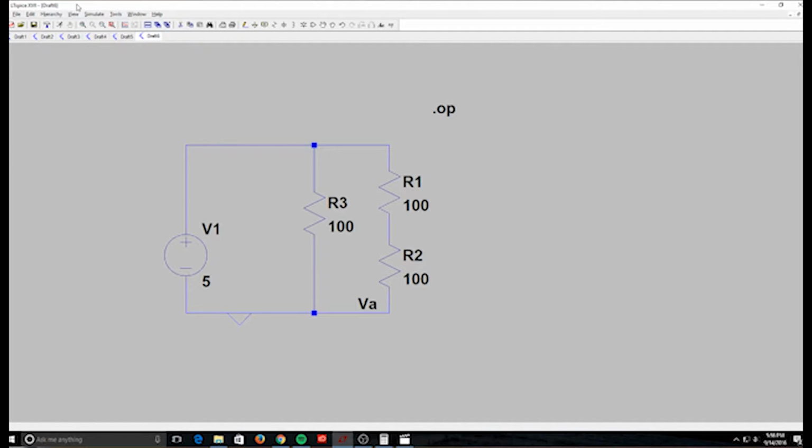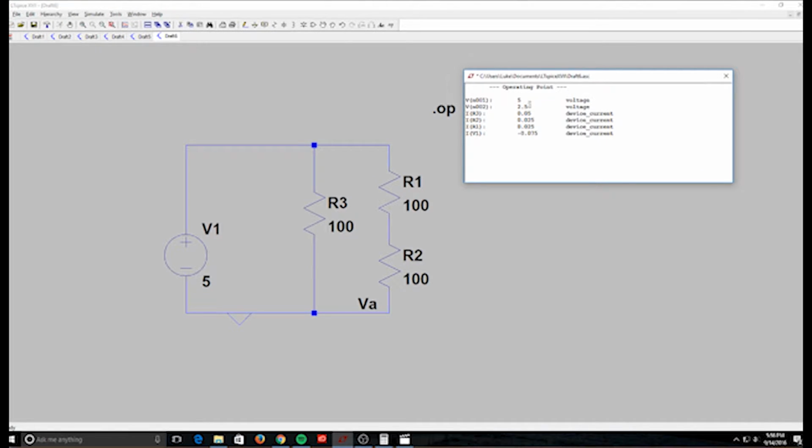Here's our last circuit with 2 resistors wired in series that is wired in parallel with a separate resistor by itself. We find that there's a 2.5 volt drop across all of the resistors. So if you end up repeating the math that Kaale ended up doing before, we get 0.25 amps of current going to the 2 that are wired in series, and 0.5 going to our single resistor that is over here by itself.